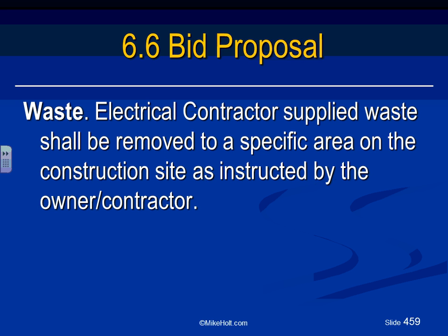Any comments? Any questions? With this chapter, dear my friends, we basically wrap the bid process, guys, from the takeoff all the way to the bid proposal. So the whole estimating bidding process, from understanding the scope of work through the takeoff, through the labor and pricing and totaling and bid summary, and also break-even with overhead and profit, all the way to the bid analysis, down to the bottom line, the bid proposal.